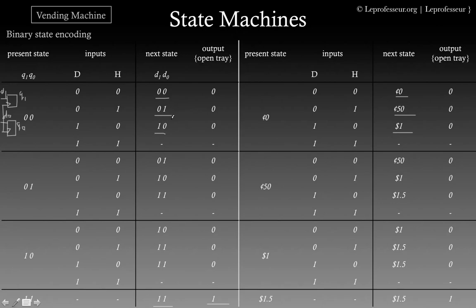Okay. So in practice, we typically use one hot encoding, or if you have to use binary encoding, then in some form you change it to gray encoding. But if you are using this encoding within one clock domain, you are fairly okay, you might get away with that.